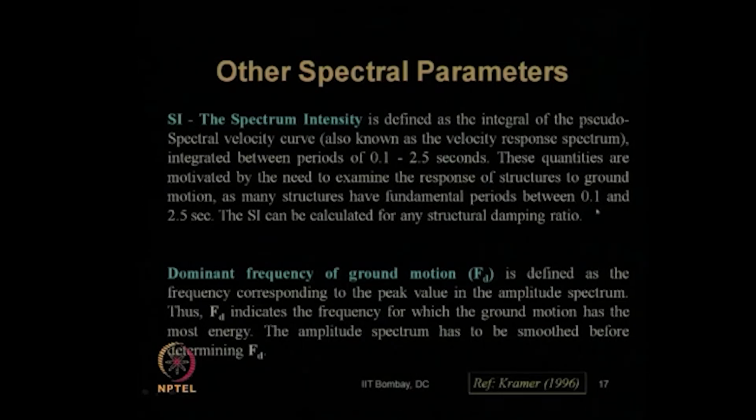So, this is the typical range of the fundamental period of any civil engineering structure. It will be within 0.1 second to 2.5 seconds. Clear? In the reverse way, considering the fundamental period of a structure in hertz, how much is it? About 1 by 0.1, so 10 hertz, right?